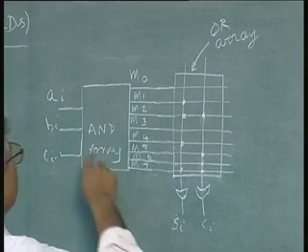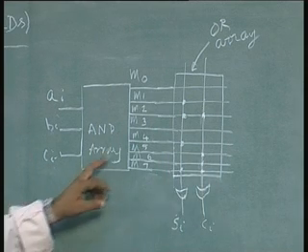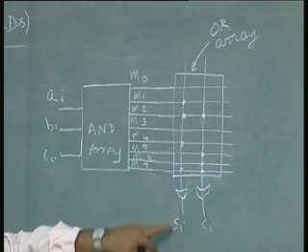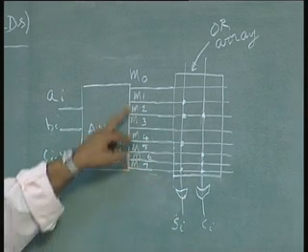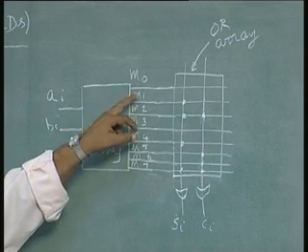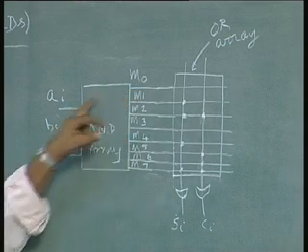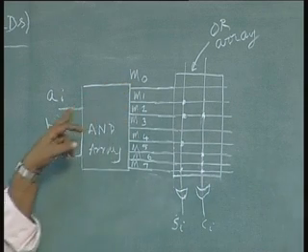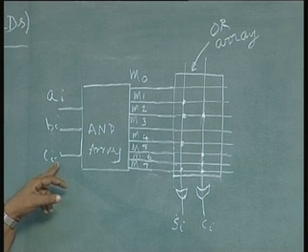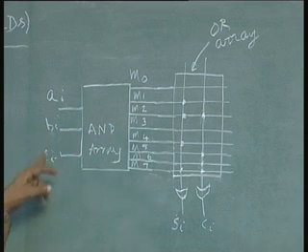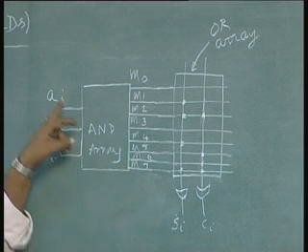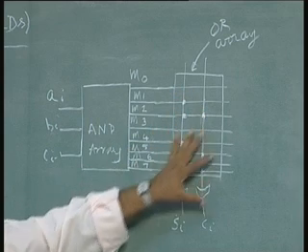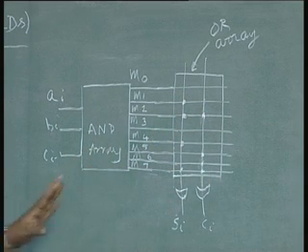So, with this array of AND gates, we are generating the minterms M0 to M7, and with this array of OR gates, we are generating Si and Ci, which are functions of the minterms M0 to M7, and these minterms are the combinations of A, B and Ci minus 1 in this case. For example, we know that M0 is nothing but A bar, B bar, Ci minus 1 bar, M1 is A bar, B bar, Ci minus 1, M7 is for example A, B, Ci minus 1. Now, this whole thing can be gotten in one chip, that is why it is called programmable.